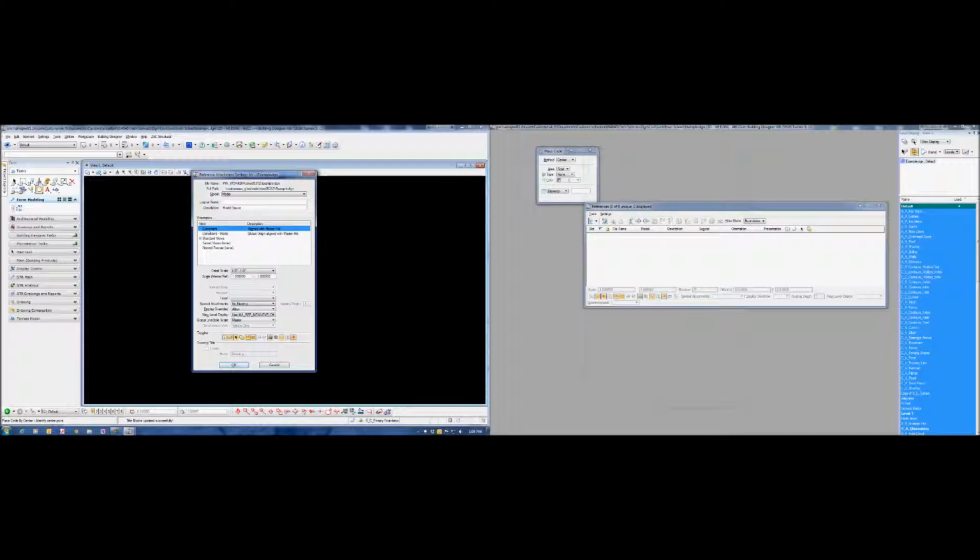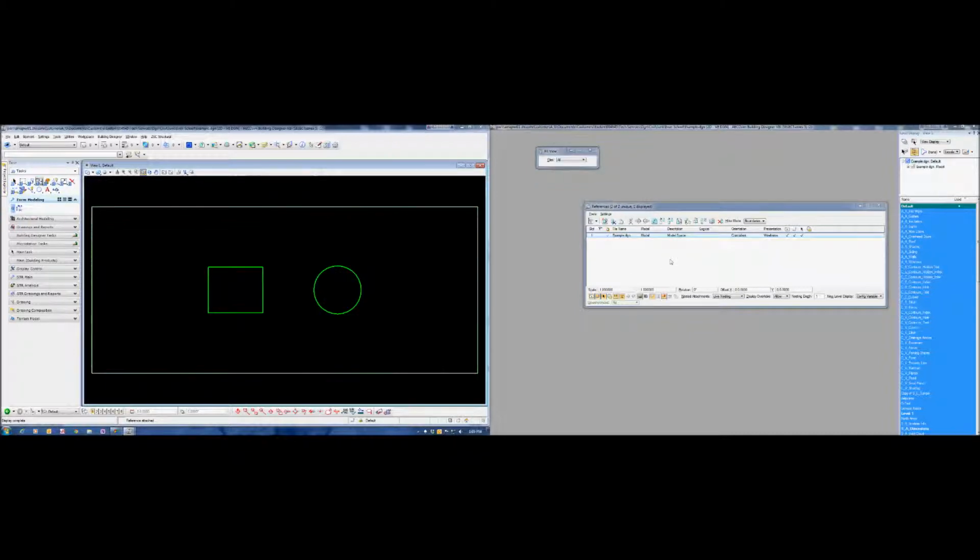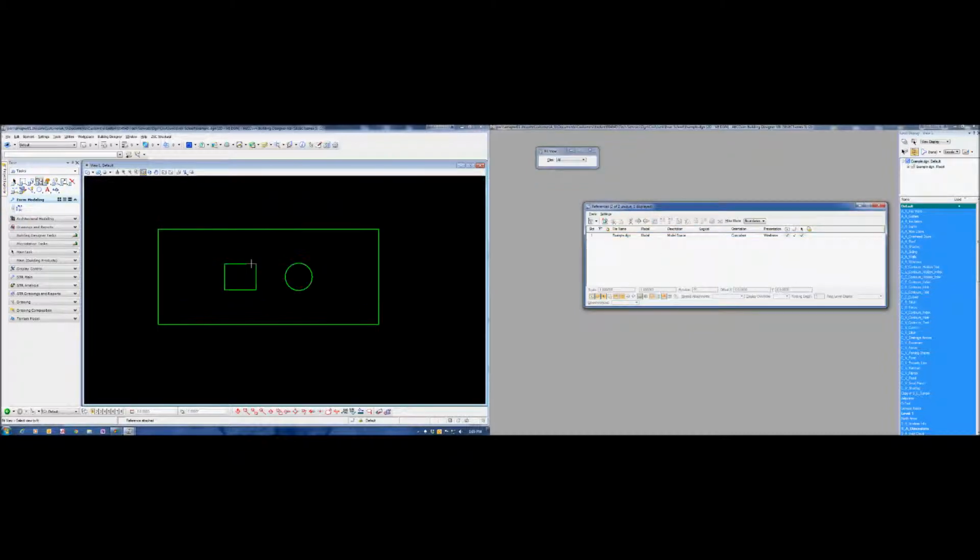At this point you're placing a plan, so you want coincident. We want this to be at a true scale, so 1:1, and we need live nesting. Live nesting is going to be interactive for steel drawings later down the road. Say OK. Fit view, and there's our plan.